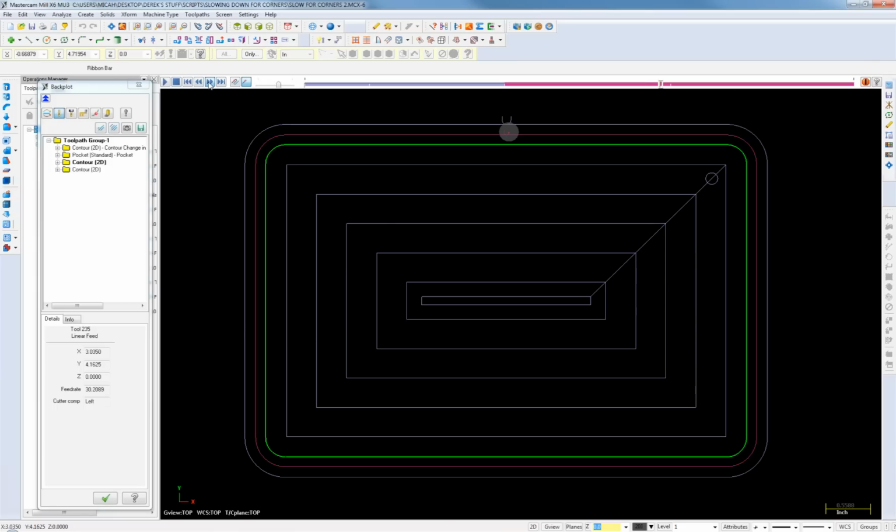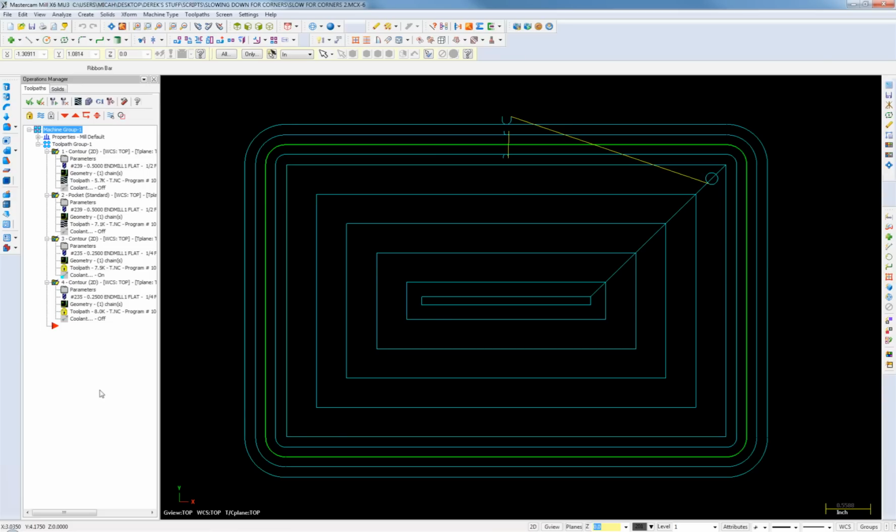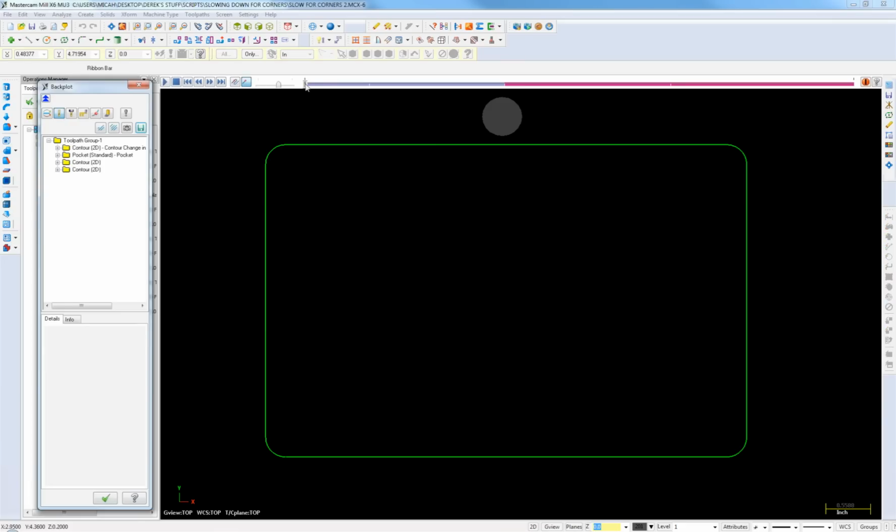Micah, actually get out of the backplot for a minute for me. I want to just show you a quick, simple tool for further reference for yourself. Because you were going through and you had multiple operations, and you were trying to backplot just one. And as you went, it was like there were multiple selected. So when you hit the backplot button at the top, it automatically selected everything that was checked. So in this case, like you're showing now.